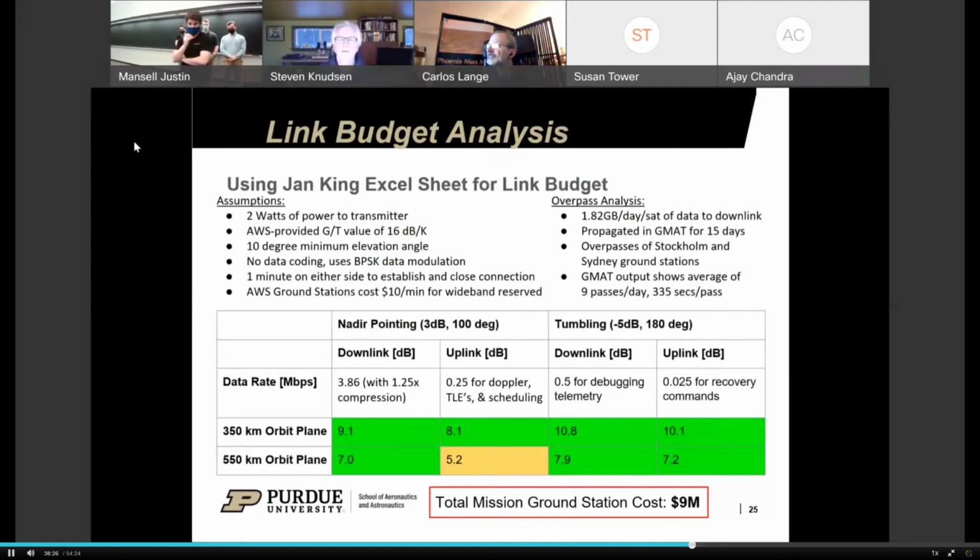So we're shooting for a 6 decibel link margin. This is kind of the standard industry practice, and this is what most low Earth orbit missions aim for. SMAD is kind of the primary source for this data, but we also looked at various providers of antennas that cited as low as 3 decibels of link margin being acceptable, as well as some NASA documentation from past missions. So we were shooting for 6 decibels. But from what we've seen, even below 6 decibels, really above 3 decibels is usually good. But we really wanted to have margin here. So does that answer your question?